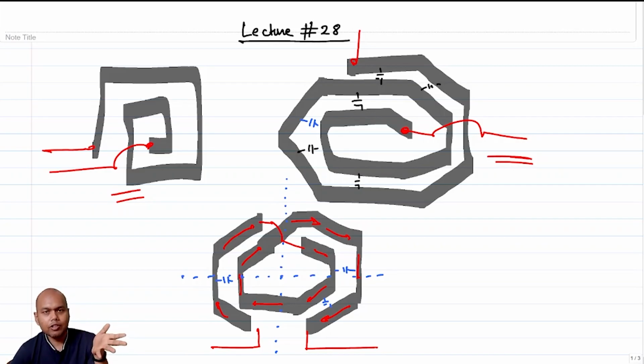And if your self-resonant frequency is lower and you want to make it higher, right? Let's say you designed your inductor and you found out that the self-resonant frequency is 10 gigahertz, but you want your self-resonant frequency to be 20 gigahertz. The easiest handle is to ensure that these interwound capacitances are smaller, which means that you have to physically space them out, right?